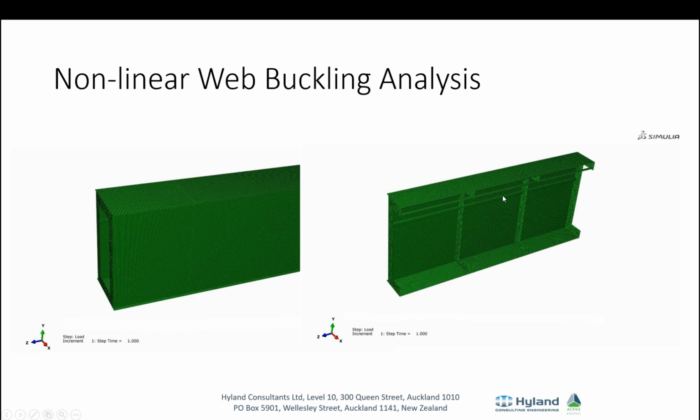So to get through this issue, potential for perhaps some buckling in the webs, it was agreed that DR would use a finite element model to verify that the loads were able to be adequately supported, and we also did the same as a verification using Abaqus.